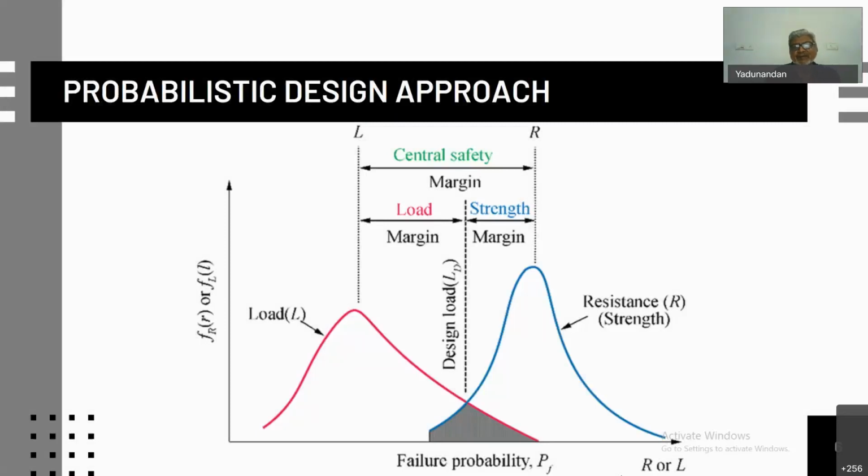So this is a fundamental basic graph for defining the performance of the structure, where we quantify the loads in terms of a normal distribution curve, the red curve. This is the variation of the various values of the loads, taken as a normal distribution curve. This is the probability of having the peak or maximum value, which is scaled up by a certain factor. We multiply the load by a certain factor so that the collapse has to occur at these magnified loads.